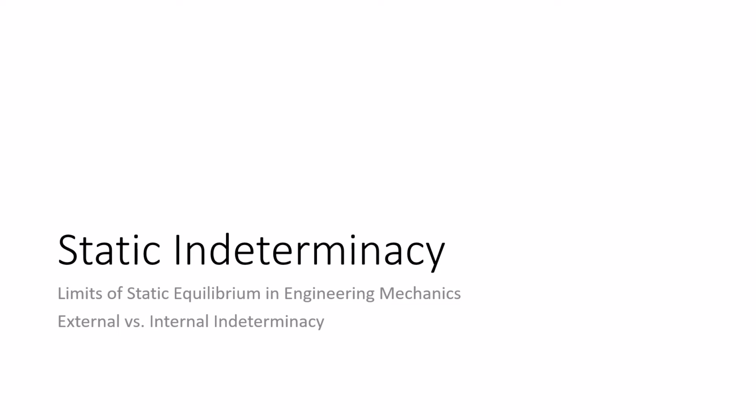I touched a little bit on this in statics, but today we really need to talk about it because, I would argue, one of the advantages of mechanics of materials, being able to relate applied loads to resulting deformations, is that we get some added advantages and some additional analytical tools to assess problems that possess static indeterminacy. I propose there are limits to what statics can do, and we're going to address some of those limits today. We're also going to look at how static indeterminacy presents itself in real-world engineering problems. And it presents itself really in 2 ways. We either have problems with internal indeterminacy, and problems with external indeterminacy. And so we're going to look at each of those.